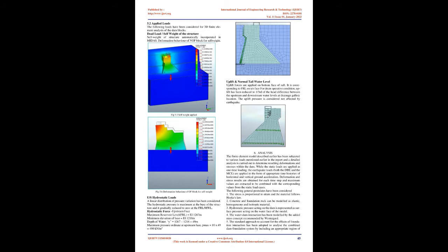There is another option in MIDAS, i.e. grid forces, which gives induced forces in each node of the model. The summation of these forces will give the total reaction. However, in ground motion time history analysis, to get reactions for each time step for all the nodes in the model is near to impossible. A sensitivity study has been carried out considering viscous boundaries and restrained ground boundaries for load combination D, end of construction plus DBE earthquake. Induced major principal stresses in NOF block with viscous boundary.